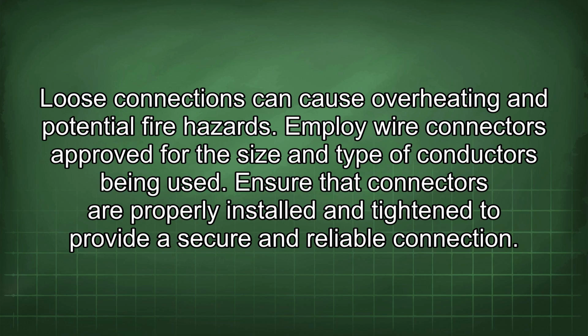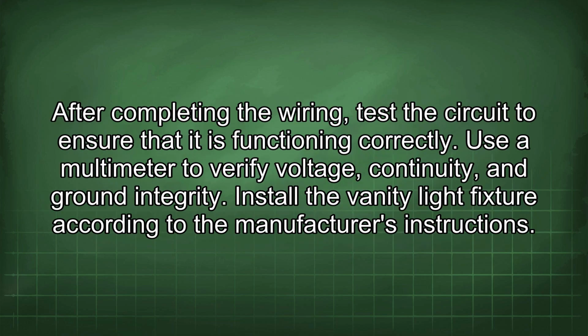Employ wire connectors approved for the size and type of conductors being used. Ensure that connectors are properly installed and tightened to provide a secure and reliable connection. After completing the wiring, test the circuit to ensure that it is functioning correctly.